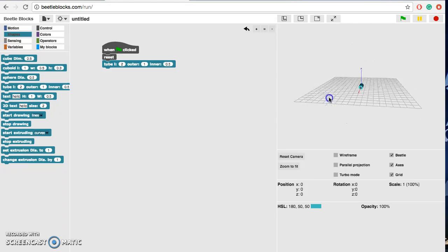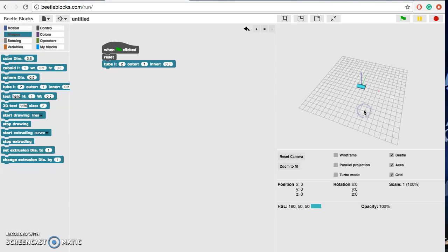So what to do if I want to make a ring? I'm going to need to measure my finger diameter, and I happen to know that mine, which I've measured with calipers, is about 20 millimeters in diameter. I want the ring to be maybe 3 millimeters thick, so I'm going to have to add 3 on either side, so the outer diameter is going to be 3 plus 20 plus 3, which is 26.